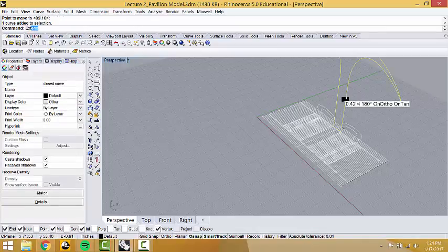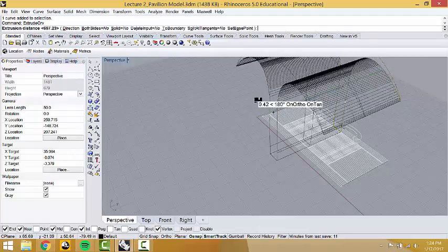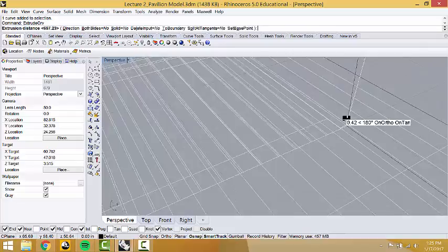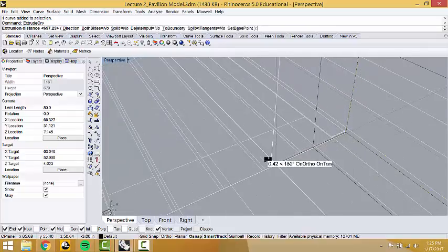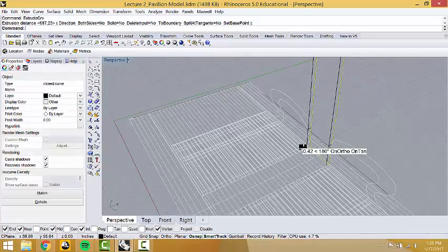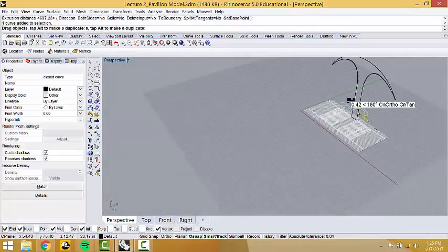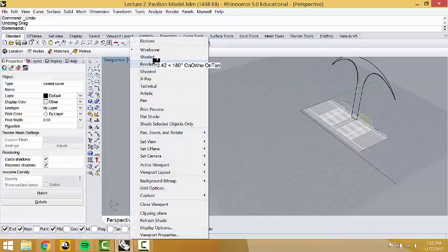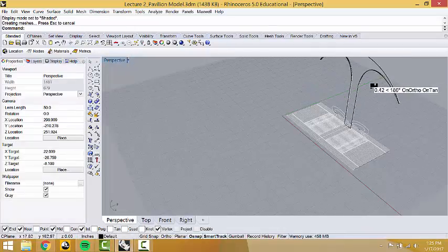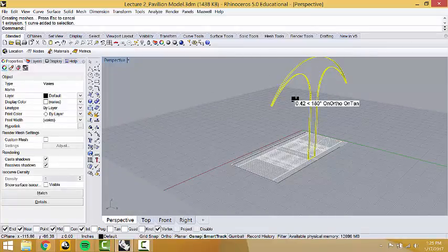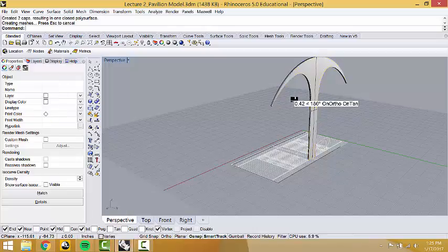I can extrude the curve. I can extrude it however I want, but what's probably best is to extrude it some sort of, again, this isn't a beautiful plan, but like that much. Oops. Shaded. Wonderful. It's not capped at all, so I'm just going to grab it and type cap. Beautiful.